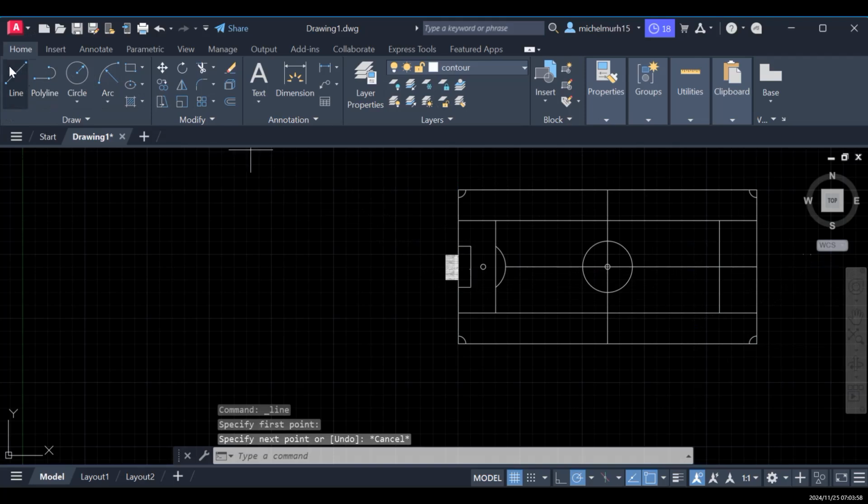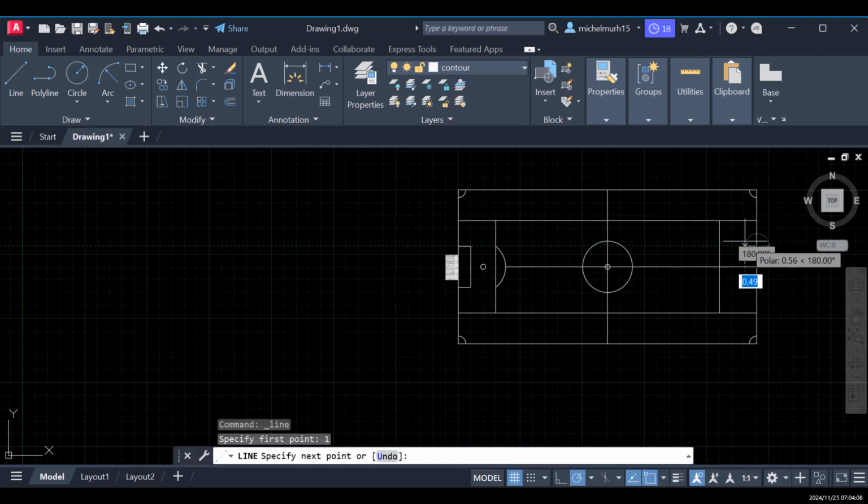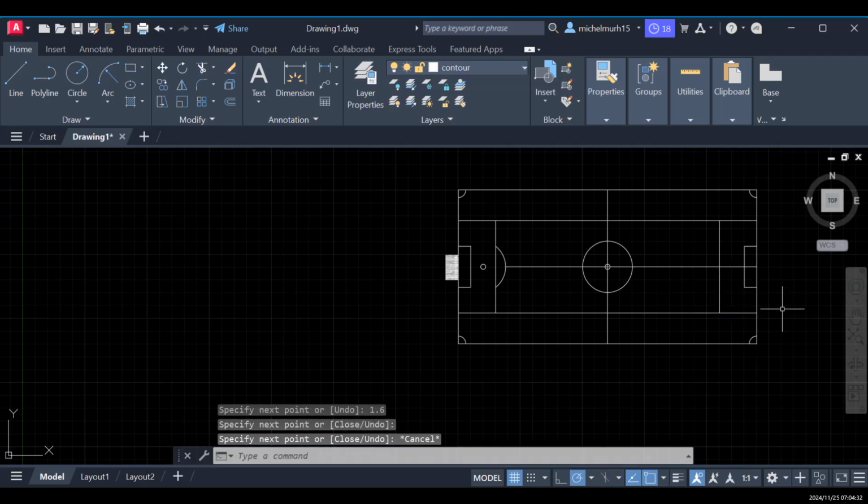So what I'm gonna do here, I will start from here first of all, and I'm gonna type 1. And then I'm gonna go on top here. If we are going top, I'm gonna go on top to 0.5. Then this should be 0.8 and this should be 1.6. The overall dimension should be 1.6. Okay, and then I can link this line together. All right.